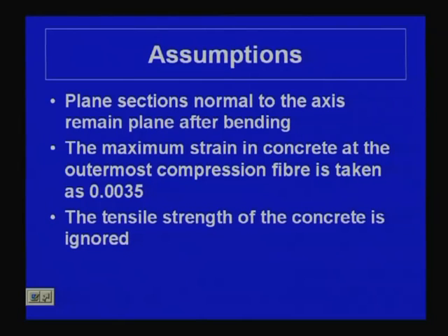The maximum strain in concrete at the outermost compression fiber is taken as 0.0035. That is the maximum limiting strain in concrete that we shall consider, 0.0035.